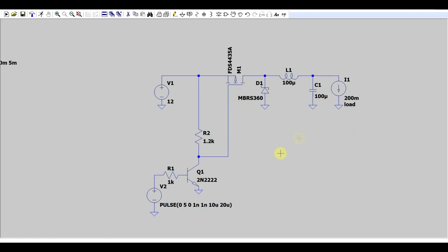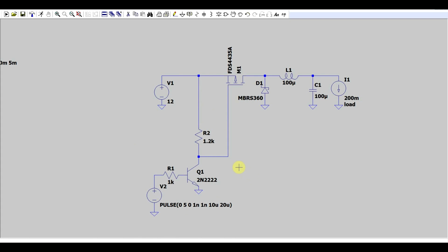And for that, let's turn to the circuit simulator, LTSpice, of course. What I've got here is the generic power stage for a buck converter using a P-channel MOSFET. And to drive it, I'm using one of the simplest types of circuit you can use. Basically, I'm taking the signal from my signal source and driving it through an open collector type of driver. And this will drive the gate of the transistor.